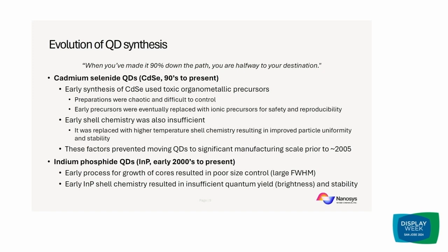There are also fundamental differences between indium phosphide and cadmium selenide in terms of how the crystal grows. You can consider a material like cadmium selenide to be more ionic in nature, so more unequal sharing of the charges in the bonding, whereas indium phosphide is more traditionally, like semiconductors that are grown at higher temperatures, a covalent system, so more equal sharing of the charges in the bonds. And chemically, it's much more difficult to produce crystals of these covalent structures at low temperatures, which typically requires much higher reactivities. So the combination of these created a lot of early difficulties in the system.